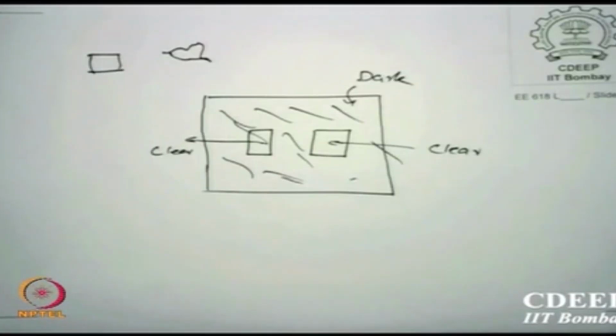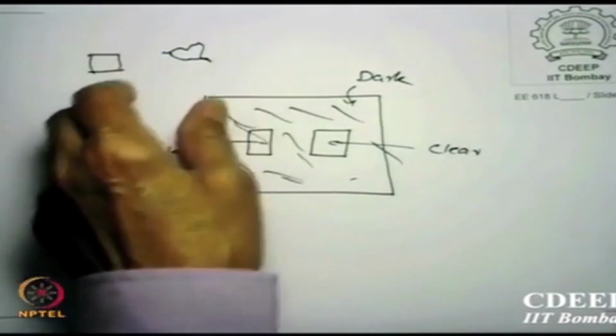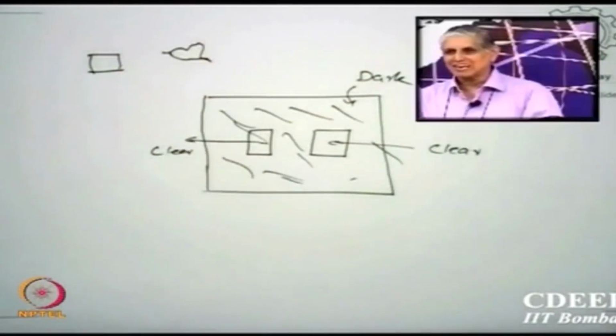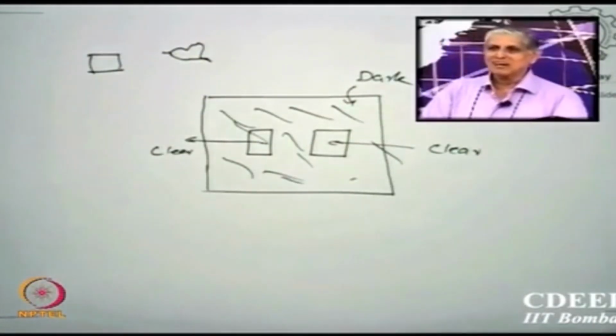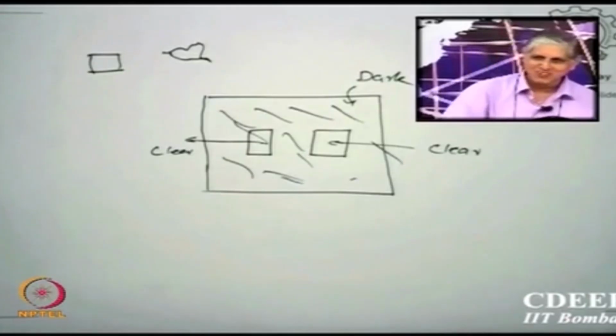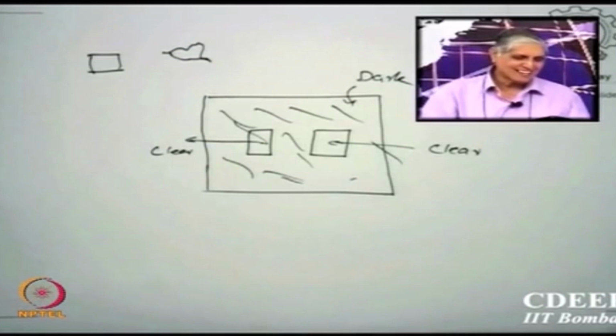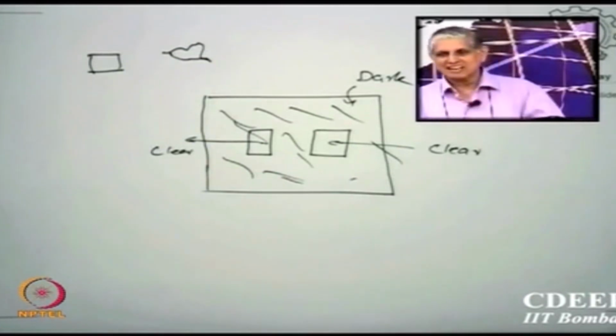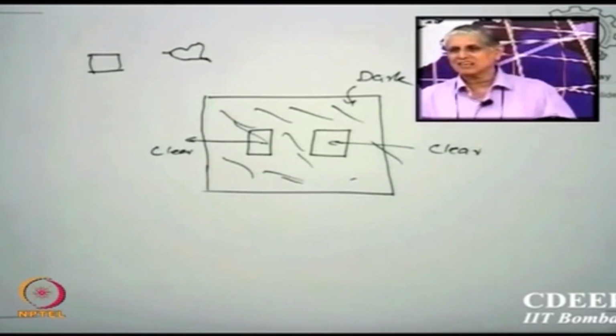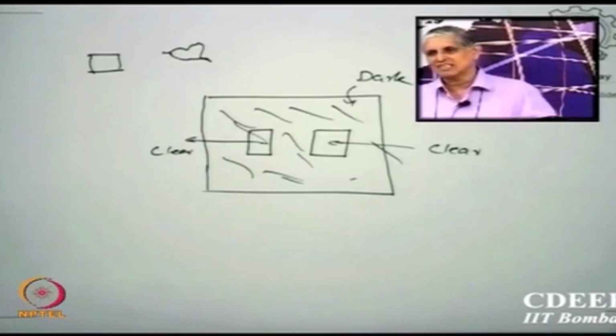So what we do is called phase masking, we do some DSP or image processing, we figure out for different patterns what you really get, do an inverse transform and see, if I want this, what should be the actual pattern. Okay. But creation of that is not so trivial. Then there is projection mask alignment. There are many techniques which are tried now for going to less than 20-30 nanometers.